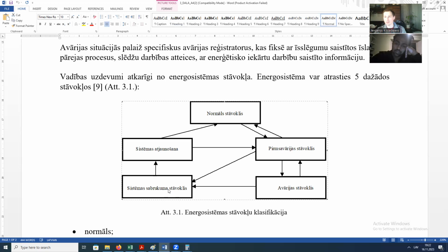In each island, there is a power station, which is continuously in operation, and some loads around this power plant that consume the generation locally, yes, in this island. But when the power system is separated into different islands, independent islands not connected one to another, this means that we have a blackout, because a united power system doesn't exist at this moment.